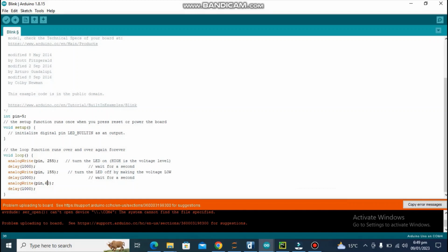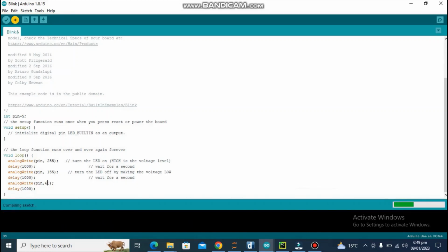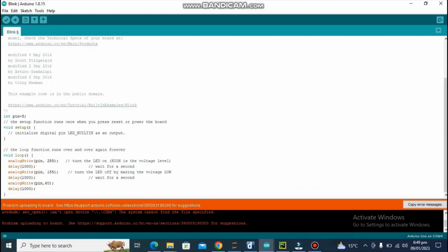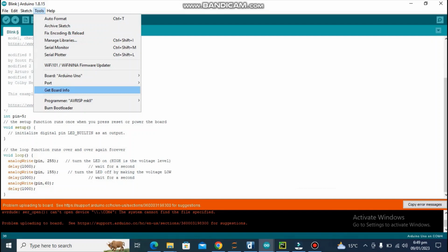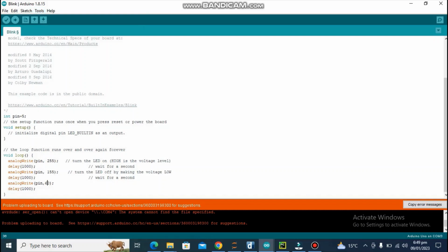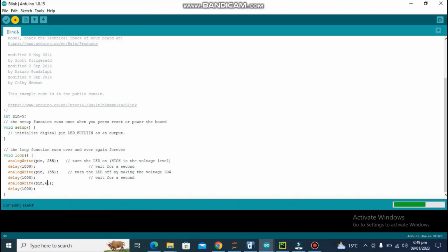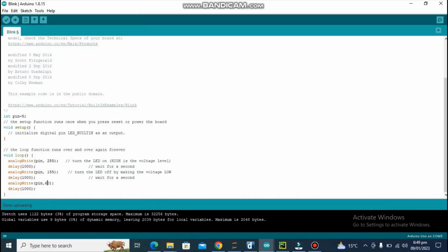So you know that to upload the program, we have to click the upload button. So here I click the upload button. It's showing some problem. I think I've not selected the right COM port. So we have to select port COM3. Now I upload the program. Program is successfully uploaded. Let's see.